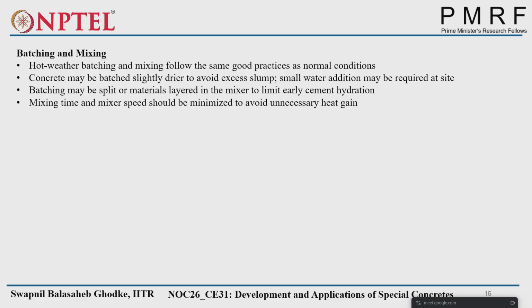We can't use ice directly. If you use ice, a certain amount of cement will come in contact with the melting water and start hydration, and until we get all the water from the ice, the cement particles will not hydrate properly. Once the cement particles get early hydration, a layer of CSH forms around them, and water cannot diffuse through that layer. So the unhydrated cement amount will be more if you use complete ice. That's why, as you saw in the picture, the ice is crushed.